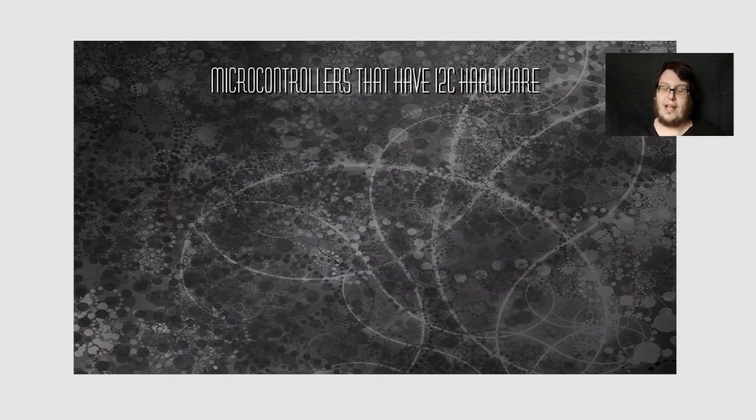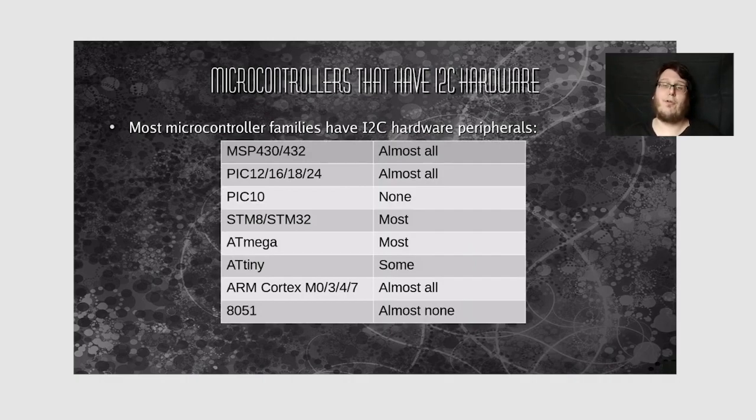So, a list of microcontrollers that have I2C hardware. Most microcontroller families do have it. MSP430 and 432, almost all of them do. Most PICs do, except for the smallest PICs like the PIC10. The STM8 and 32, almost all of them do. Almost all the ATmega and ATtinys do, except for the very smallest ones. And any microcontroller that's based on an ARM Cortex-M, no matter what size it is, M0, M3, M4, M7, it's going to almost certainly have an I2C bus, at least one. 8051-based microcontrollers usually don't have I2C peripherals. They usually have just very basic peripherals.